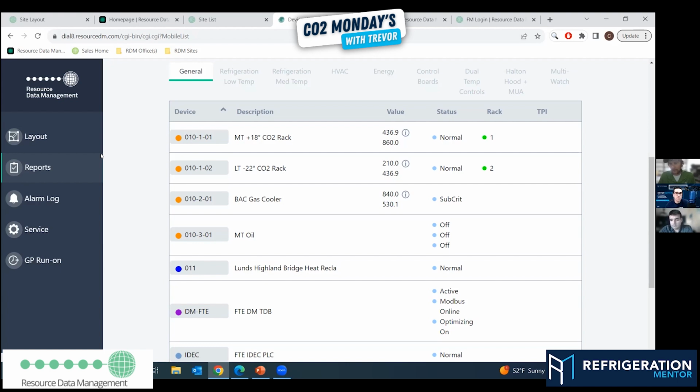You have to, just like Cody said there, it could be a sensor. It could be a temperature probe. It could be a parameter even. Maybe it is a controller thing, but the chances are if it was already running for 6 months or a year, it's not the controller. It's usually a mechanical issue that's causing a problem.